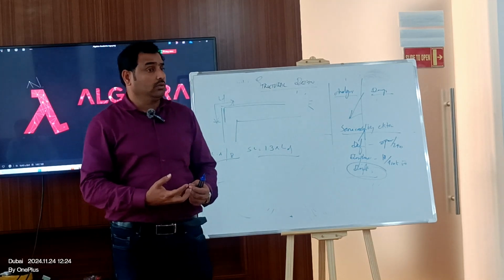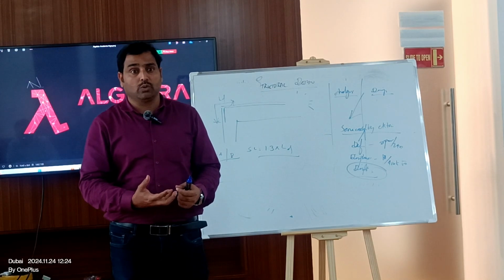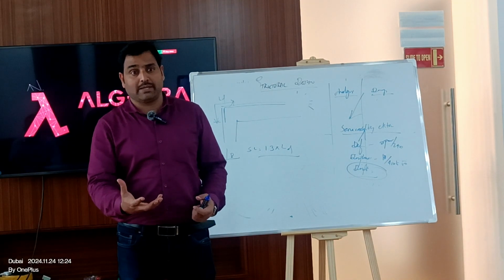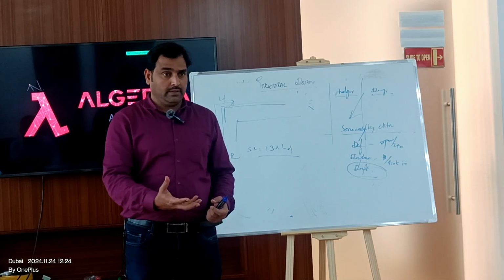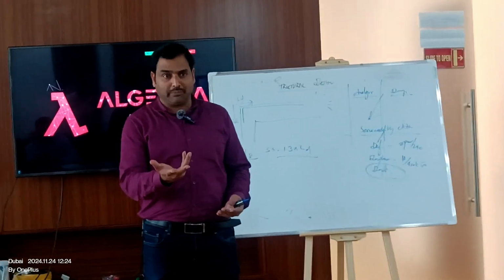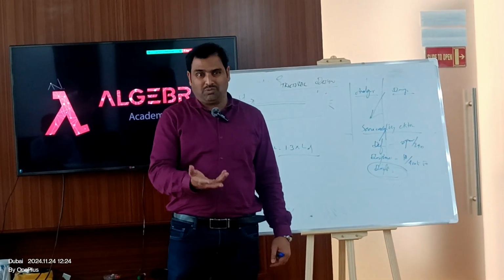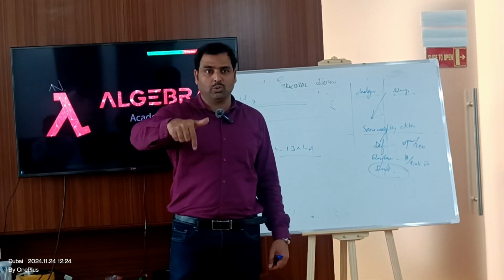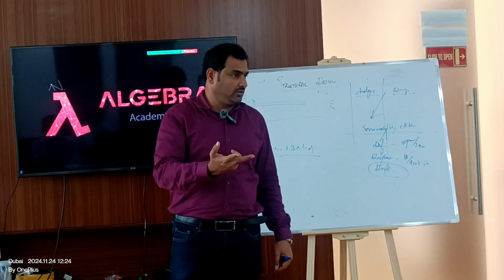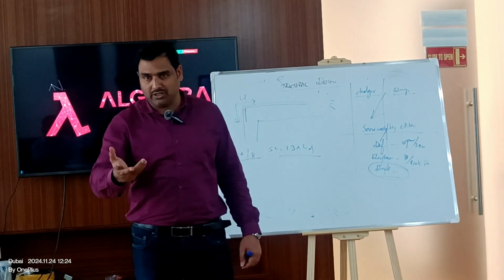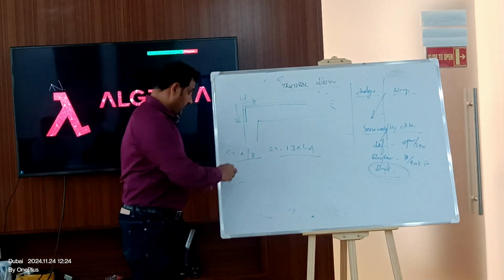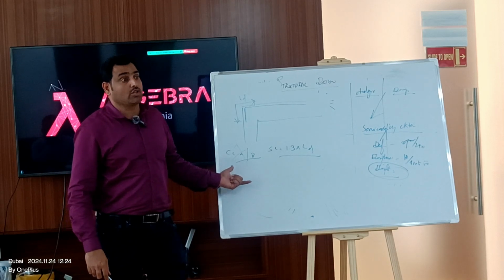Where you don't have higher forces, where you don't require more bonding, where it is not going to act as a full structural element, the best example is the grade slab. Other than that, everything is a structural element. The grade slab is the one where you are going to use 8mm dia, 10mm dia, right? Not more than 10, nobody is using. Unless you have heavy load, what you call racking load, or else you use 10mm. It might go for 2 layers, single layer to 2 layers. But nobody is going to use 12 at 150, 12 at 200, similar to suspended slabs, right? We will not use class A rebar; you are always using class B rebar.